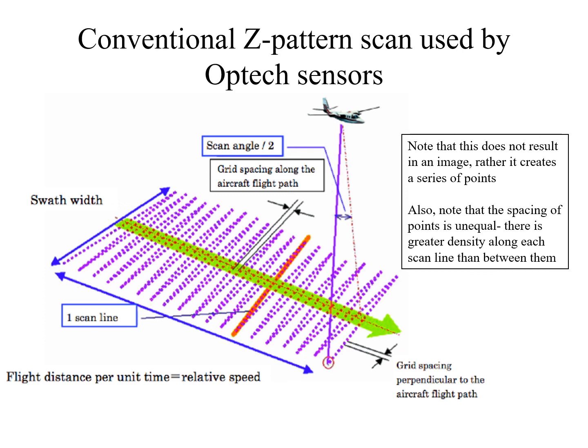But in fact, if you look at it carefully, what you'll realize is that there are large areas between each of those cross-track swaths where there's no data. So there isn't one number that can describe the number of returns on the ground surface. There's a distribution. Some areas have more, some areas have less. And that's just something to keep in mind.